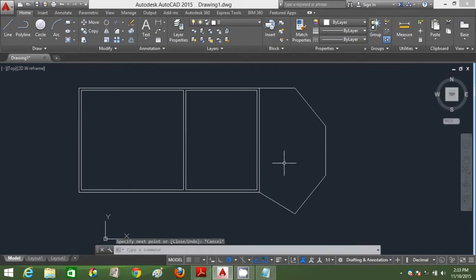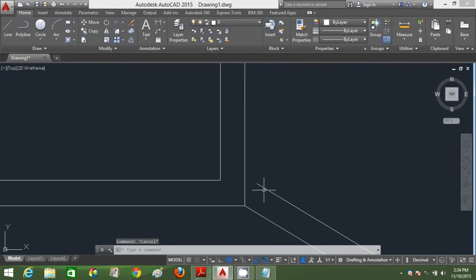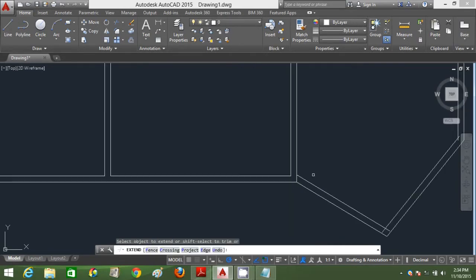I'm just going to join this to the other point and click offset. Click offset, type in 200 mm as its distance, and offset this wall inside. Alright. Okay, as you can see, if you zoom in on this particular portion, this line is not going to the maximum. Alright, I'm typing EX and enter twice to extend this line. So type EX and press enter twice, double enter.